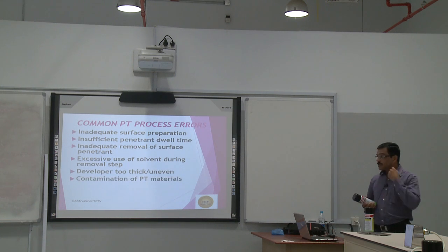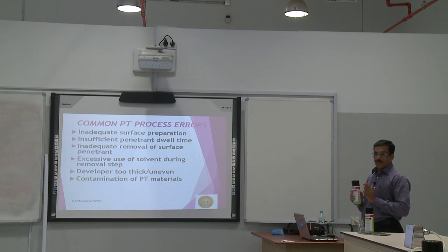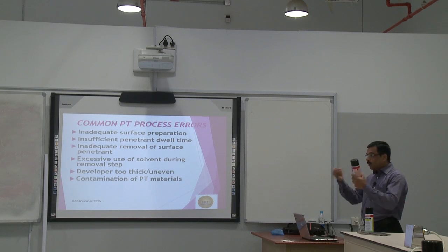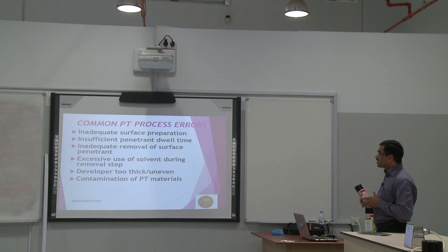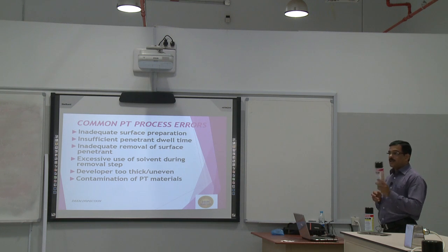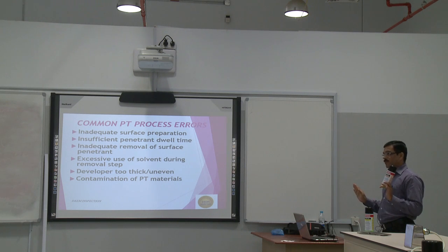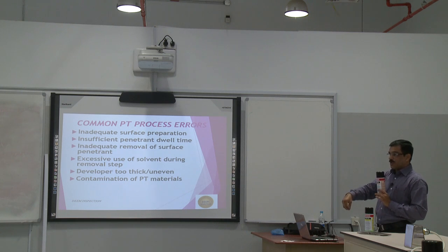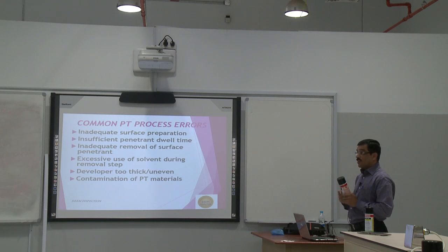So, common errors. If the surface preparation is not adequate, if you are not cleaning the surface properly, there is a chance of error. Too many different indications will come. Similarly, insufficient dwell time. Suppose they say 10 minutes, and we give only 2 minutes and remove the penetrant, maybe there is no chance of indication, because the penetrant did not get enough time to enter the discontinuity. So dwell time is important. And inadequate removal of surface penetrant.